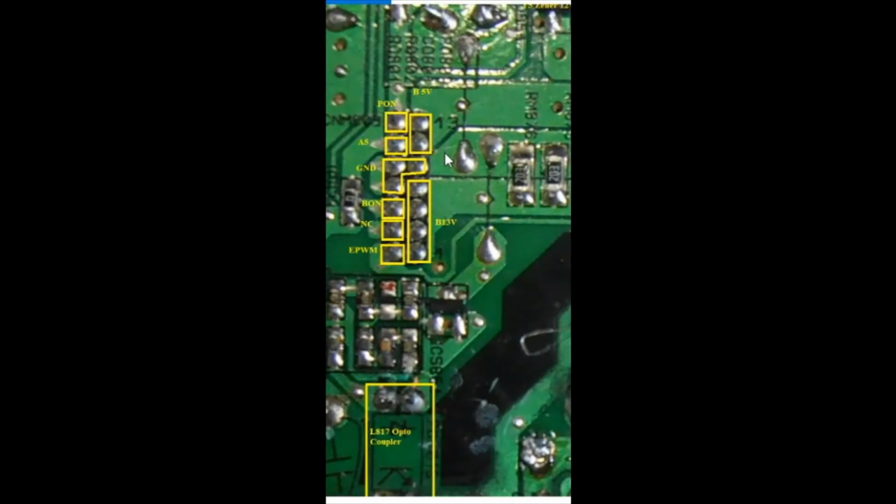The output connector: what are the outputs that it gives, as well as what are the inputs it gets for the board to operate. If you look at this, I figured out that from one side, let's say a 13-volt output is given by 4 pins of that connector.